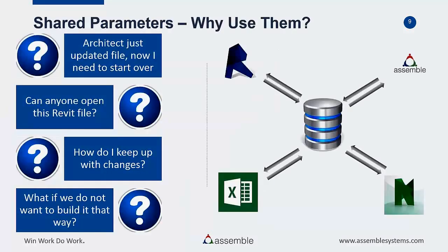Then we realized that we needed to push a lot more information back to the modelers. The pre-construction managers wanted to break this model up in many different ways. One of those ways, because we were looking at concrete, was the strength of the concrete. And just because the designer said that all the floors needed to be 6,000 PSI concrete doesn't necessarily mean that's how we were going to build them.